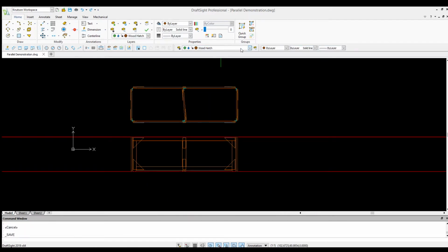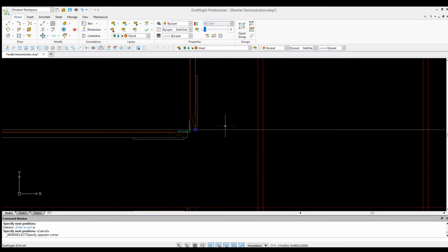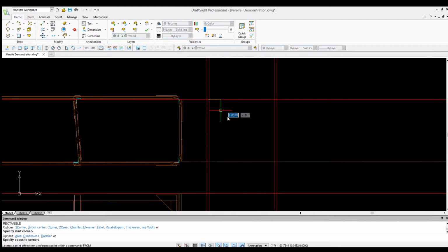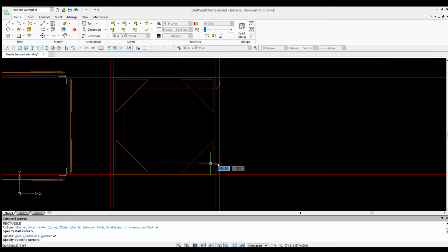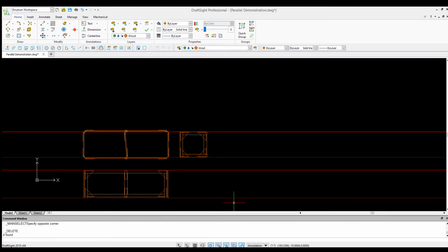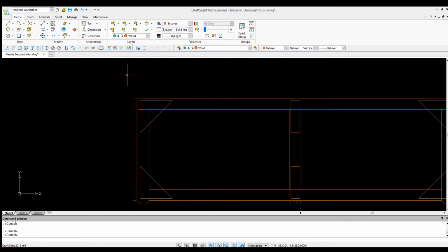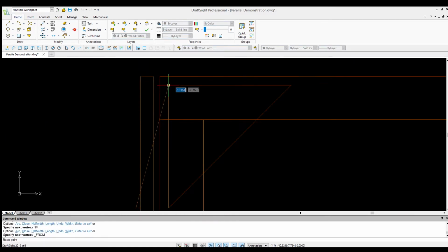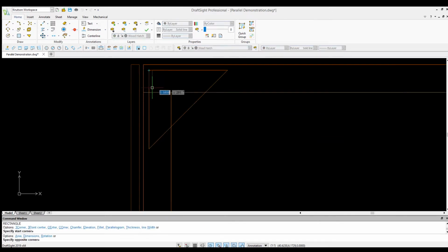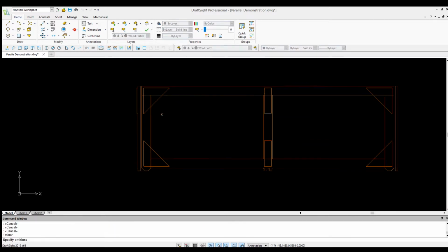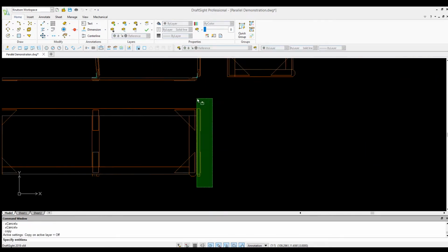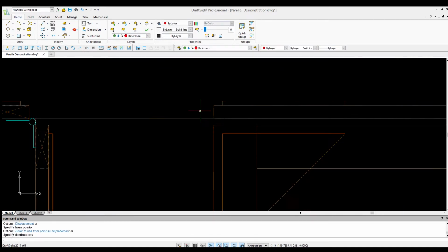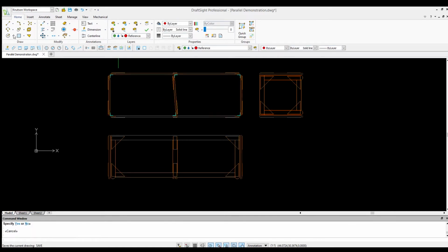I nearly always begin with a plan view of the item I'm drafting. Plan view just means looking straight down at the top surface. This is the same sort of view you see in a full ground plan. Then I follow up with front and side elevations, which are the straight-on views from the front and side of the piece. This parallel unit is symmetrical, so I don't need to make separate drawings for the back or opposite side. There are times when I do draw all views, particularly when I need to specify drilling patterns for bolt holes or any atypical framing.